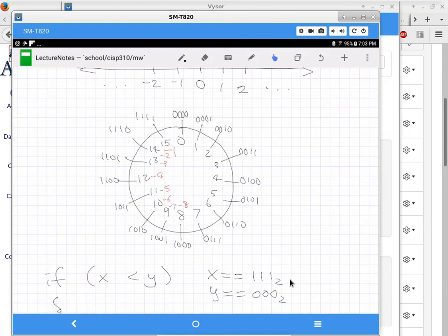The computer doesn't need to know. With all the carry look-ahead, adder, and subtractor circuits, it doesn't really care whether you're dealing with a signed value versus an unsigned value. Okay, because there's no need to. The adder circuit will work whether you're dealing with signed or unsigned. Let me explain why I said it would work in either case.